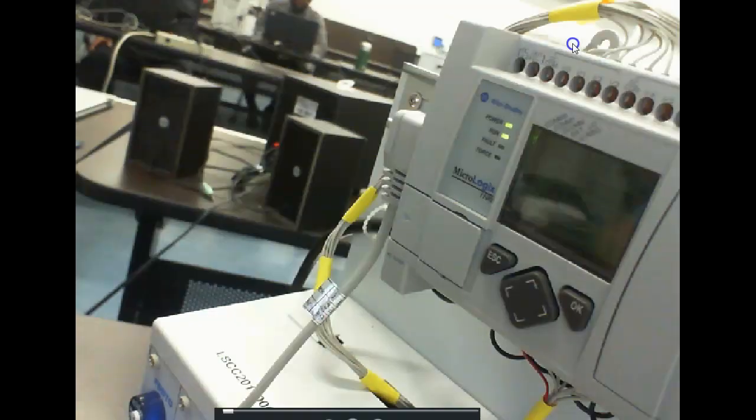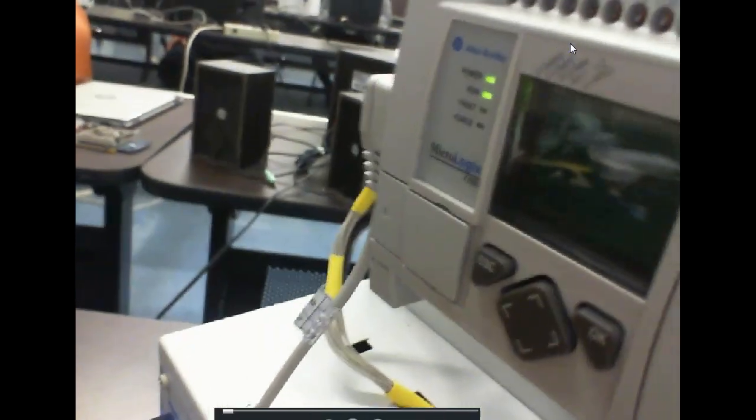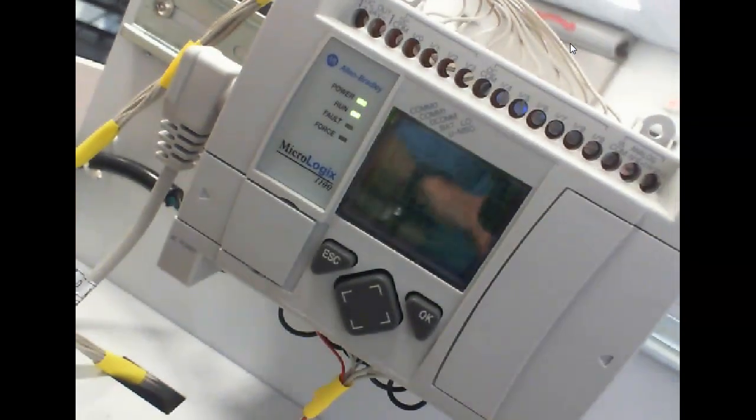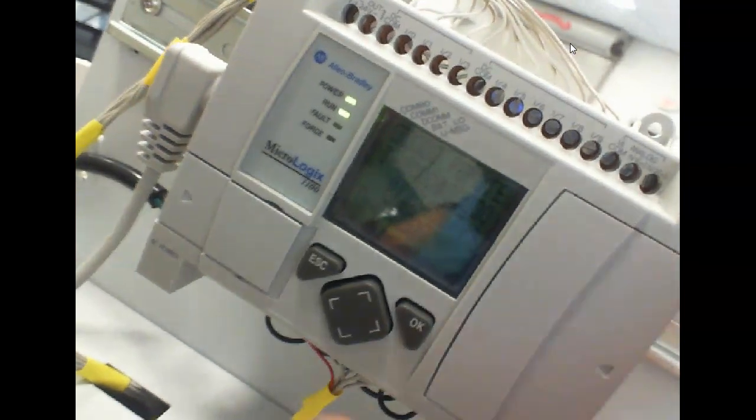So up here on this panel, if y'all can see, I'll try to put it where y'all can see it. I can hit escape, and one of my options now is I can go down here to mode, and I can switch it to program mode. Now, this guy right here, I couldn't switch it manually. It says the PLC's in run mode, right? You couldn't do anything with it. Okay. And I could come up here and switch this in offline.